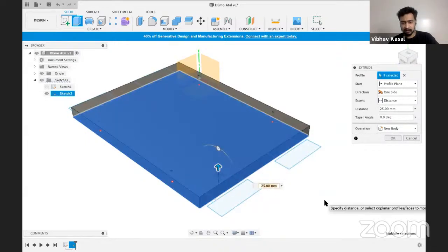Okay, now I got this, but you are laser cutting it, right? Even though you're laser cutting it, it only takes the top profile of the thing. You just need a line. The thickness is not something that we have to consider now, but still, for the sake of it, I will still consider my material and what thickness it is. The material that you get in the market is something that you should know whether it can be laser cut or not. If you are able to laser cut, what is the thickness that you are giving?